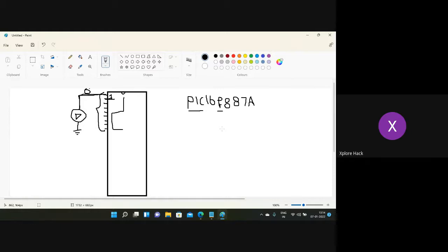Since we have the program memory or the storage space inside the microcontroller, you are able to store the program instructions inside it, through which you can control the actions, or the output, of IO devices. Okay, so that's the reason we are using a microcontroller over here. To mention the difference with this microcontroller, we have used F, that is, flash memory is available, and then 8. So totally we have 8 input and output pins.